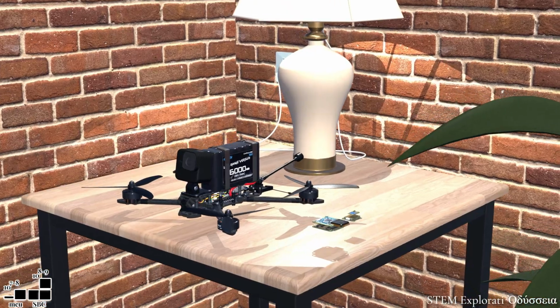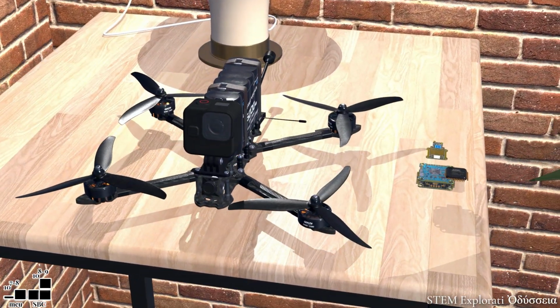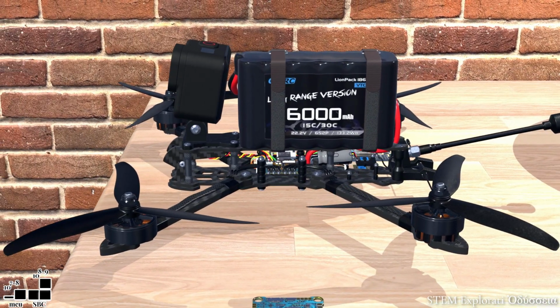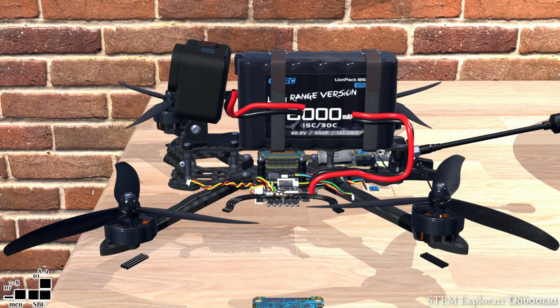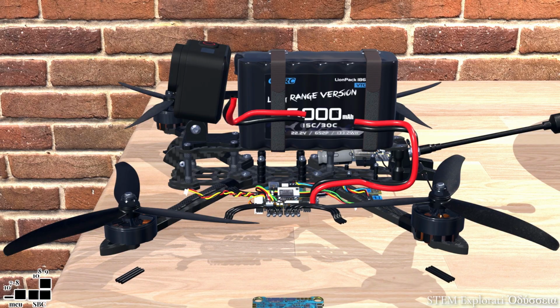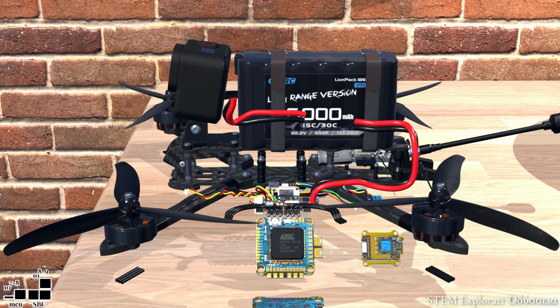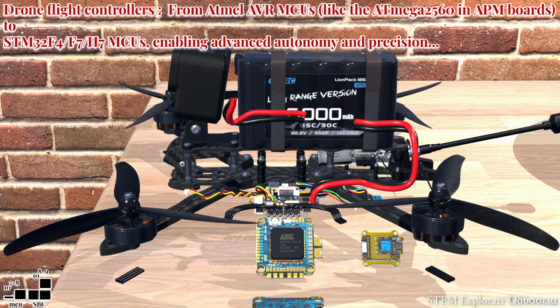Another exciting use of microcontrollers is in drones. At their core, drones need to constantly read data from sensors like gyroscopes, accelerometers, and GPS, and then adjust the motors to keep the craft stable in the air. These are real-time control tasks, and a mid-range microcontroller is more than adequate to handle them. Chips like the STM32 series or the Atmel AVR microcontrollers are very popular choices for flight controllers because they're reliable, efficient, and provide just the right amount of processing power for stabilization and navigation.